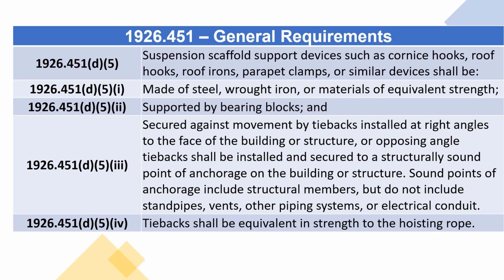Sound points of anchorage include structural members, but do not include standpipes, vents, other piping systems, or electrical conduit. Tiebacks shall be equivalent in strength to the hoisting rope.